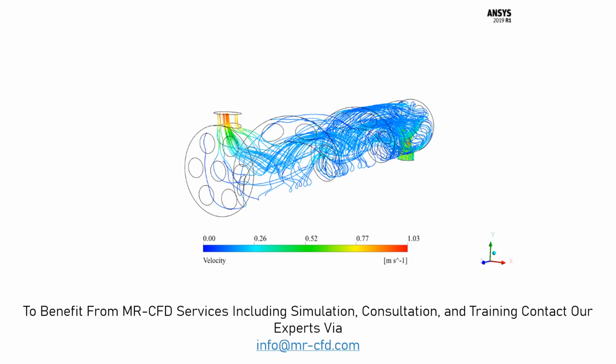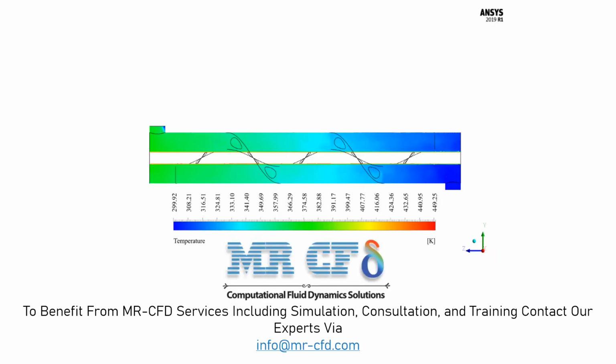Now in this slide, you can easily see the streamlines of the water flow inside a heat exchanger. Now in this contour, you can easily see the effect of baffles causing the water flow to rotate inside the heat exchanger space. Now in this 2D contour, you can easily see the temperature changes from the inlet boundary to the outlet, where the temperature has increased due to the heat transfer between the water liquid flow and the inner tubes.